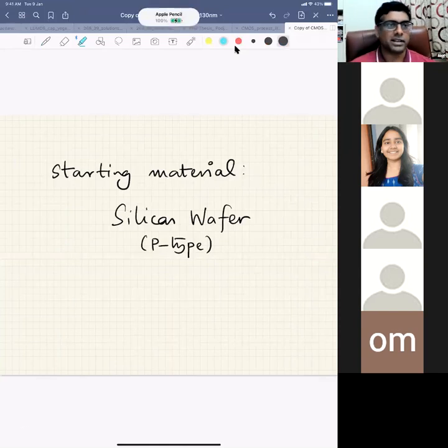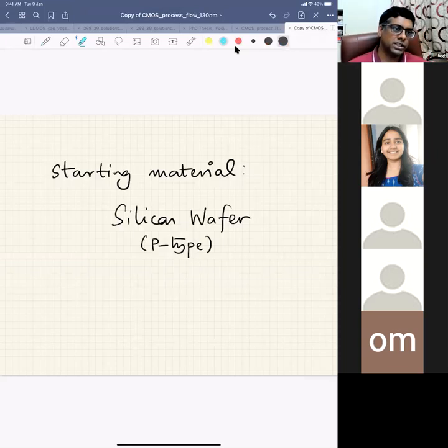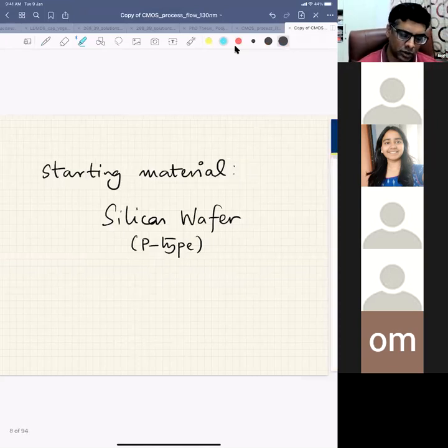The starting material, right? So the starting material, when you do CMOS fabrication, is silicon wafer, right? So silicon wafer, we generally use P-type silicon wafer. So we use P-type silicon wafer with different resistivity, right? To start with. So when you talk about wafer, right?